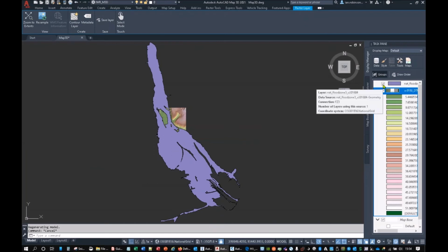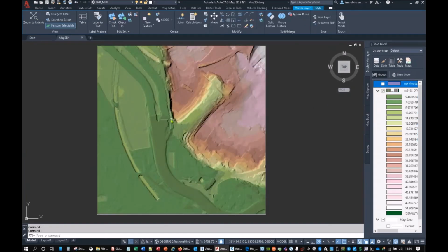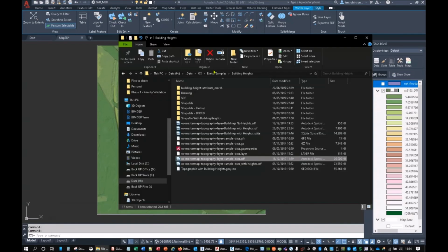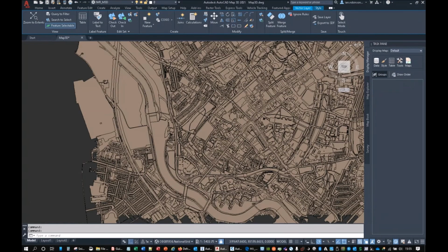Now I know a lot of you ticked that you use your mapping data in DWG format. You don't need to. If you ticked, I'm an AutoCAD user, and you also ticked, I get my maps in DWG, and you also have a spatial database with a load of GIS data, don't use the DWG, use the spatial data files. So if I go in and find the OS master map here, just drag and drop it in. That's another option. There it is.